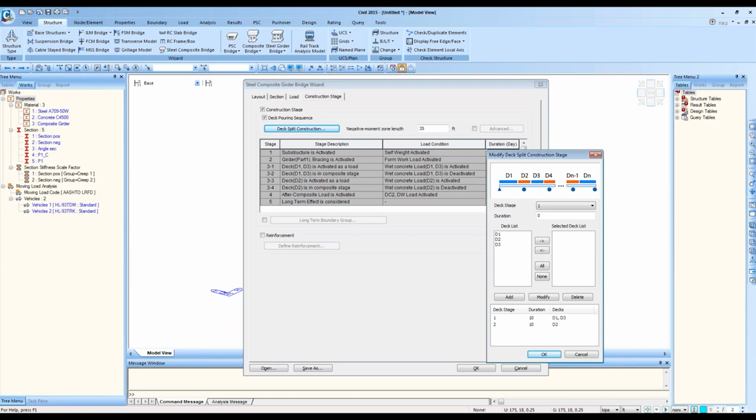You can refer to this picture here. D1, D3, for our case, we only have 2 spans. So only up to here, right? And D4 is not there because here the negative flexure doesn't occur. So we only have D1, D3 in the positive flexure zone and D2 in the support area. And how do we know how much of the length each D1, D3, or D2 is covering?